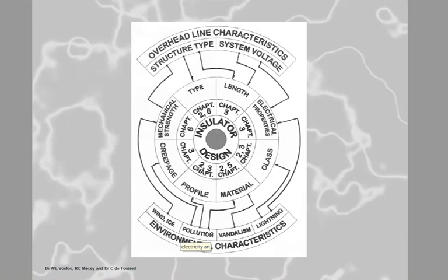What is L? Length. And that's your creepage distance. Cool. So the higher the creepage, the higher R, the lower I. You got it? Now, the thickness of the pollution layer. The thicker the pollution layer, the larger the area available for current flow. So A becomes bigger. If A becomes bigger, what happens to R? Smaller. R becomes smaller. What happens to I? I goes up. What do you want? I as small as possible. So you wash, you clean, you get rid of the thickness, you reduce the area available for current flow. Cool. So L, increase creepage, and rho, A, you reduce.